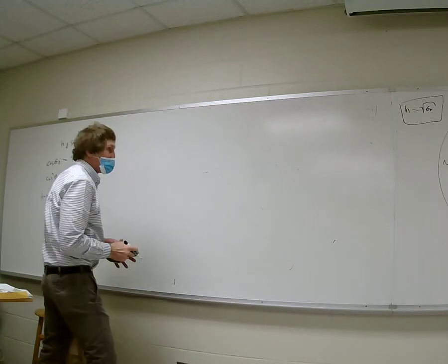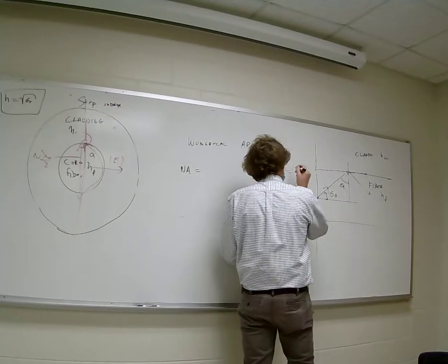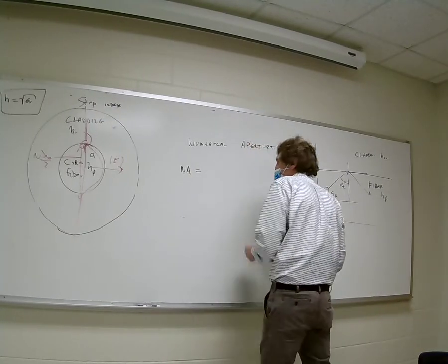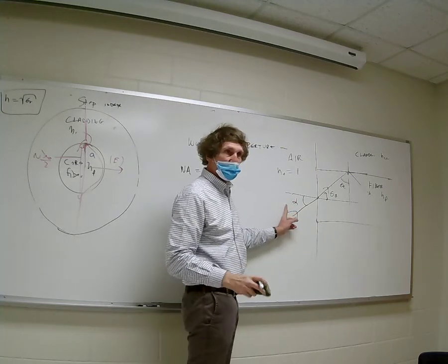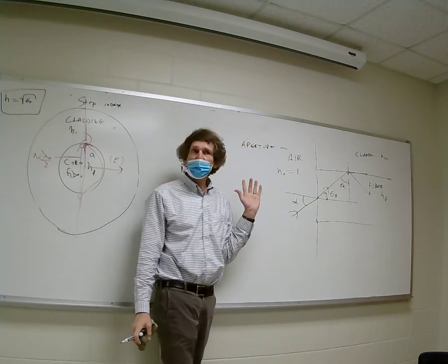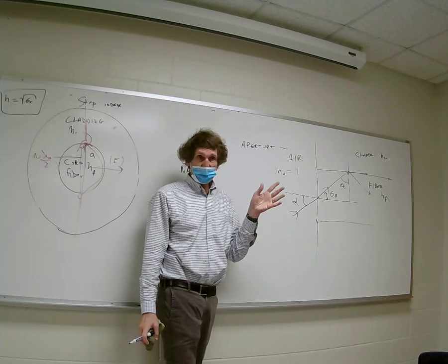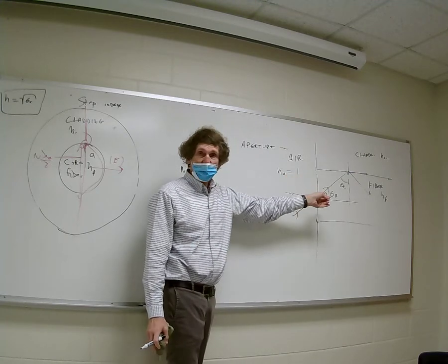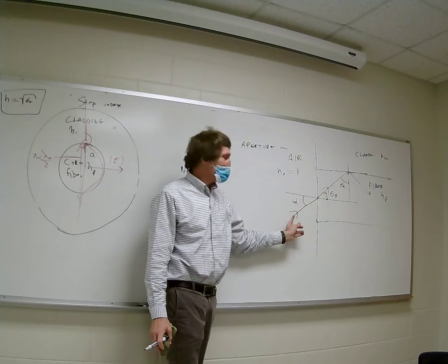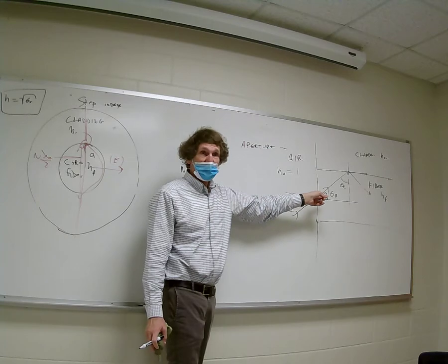Now if I have this, I come back here. That's N fiber, this is N0. Typically it's equal to 1. We're talking usually about air. So now I come down here and I'm going to use Snell's law again right here. Remember what Snell's law says, if we're assuming we have a dielectric that's lossless: the index of refraction on one side times the sine of this angle is equal to the index of refraction of that side times the sine of that angle, correct?